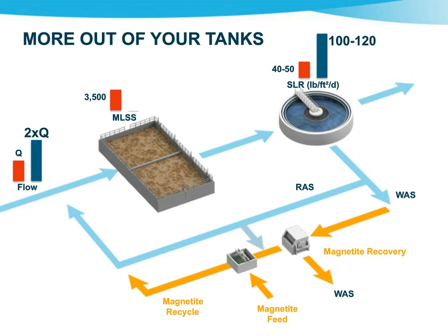We've done quite a few BIOMAG retrofits to existing applications that needed increased capacity, both hydraulically as well as treatment performance. They go from conventional to ENR, enhanced nutrient removal, carving up the tankage and putting in anoxic zones so they can nitrify and denitrify.